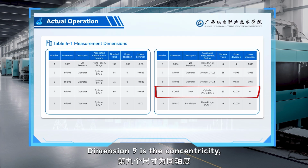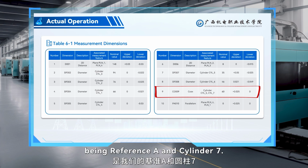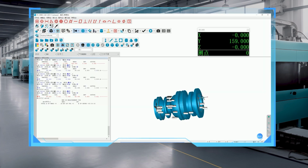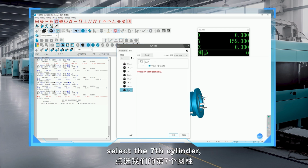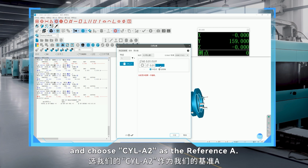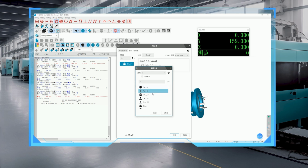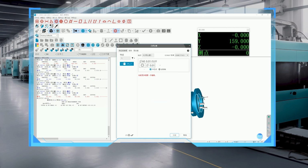Dimension 9 is the concentricity, with the associated features being reference A and cylinder 7. Click on the evaluation in concentricity, select the 7th cylinder, then click on the reference definition and choose CYLA2 as the reference A. Click Create and close the concentricity evaluation window.